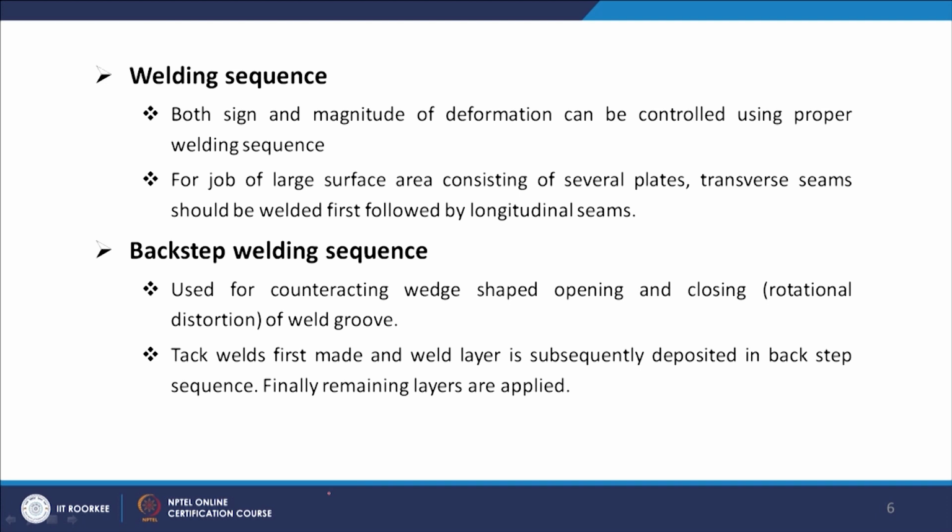That way we do the welding sequence, and after that you apply the layers continuously and alternating, so that way you move. In these cases there will be good melting through of the initial sections of the welds, and the workpiece warpage will be diminished using this backstep welding sequence.